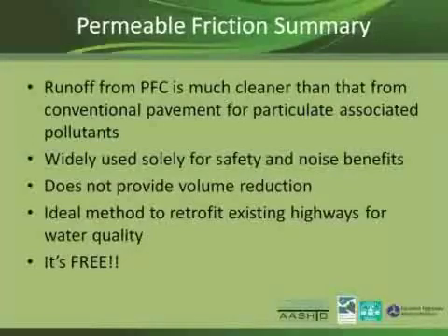So the idea is, look, here's the pavement. The water quality of particulate-associated pollutants is fantastically better. You're seeing 80 or 90% lower pollutant concentrations. And the trick is, DOTs are using it all the time. In all of those studies in North Carolina, California, and Texas, none of those were installations specifically for water quality testing. Those were all sections that the local DOT or district offices had done on their own accord just because of the safety and noise benefits.